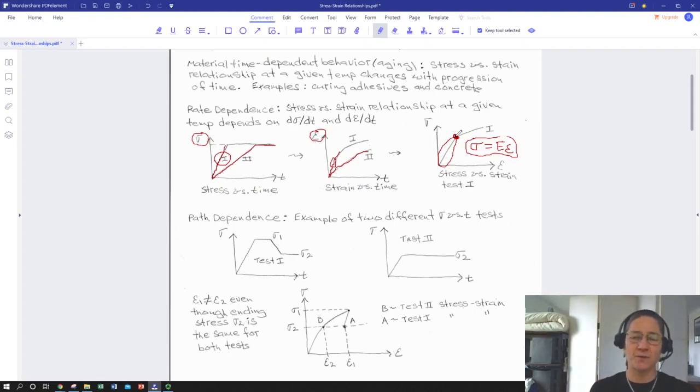With polymer chains, we might get a little uncoiling. If you're familiar with polymer chemistry, most thermoplastics at least are coiled chains, coiled around their bond axes. They can rotate. They'll uncoil a little like a spring being basically twisted open a bit.